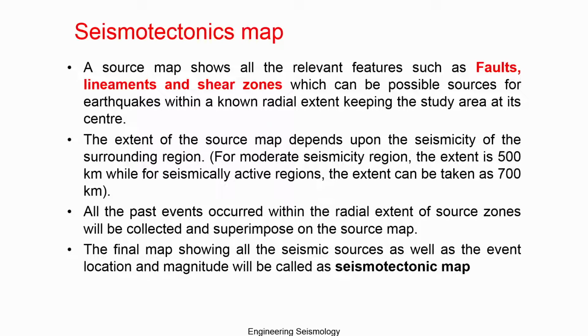You should not take a map published 10 years back by somebody and do the hazard analysis. If you do that, you will end up in trouble in deciding your seismic study area. So this will help you estimate more reliable hazard values as we map all the possible seismic sources through this kind of detailed analysis.